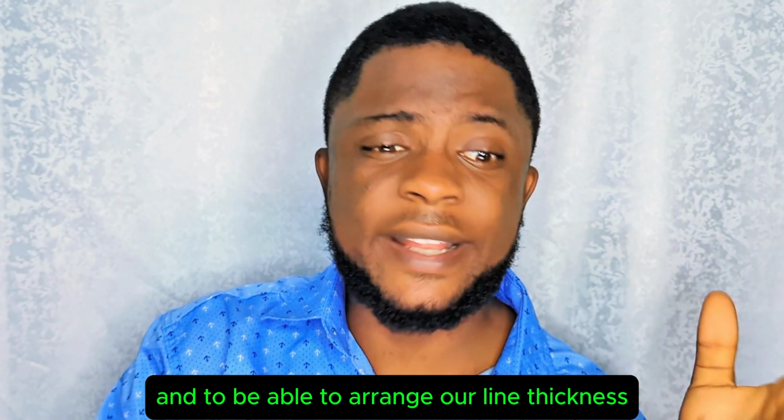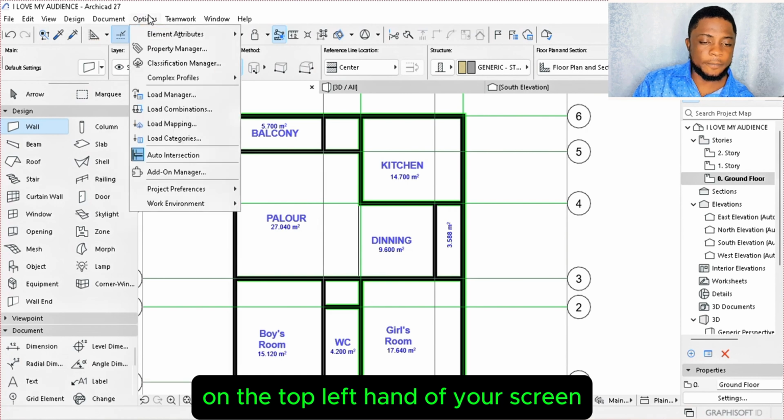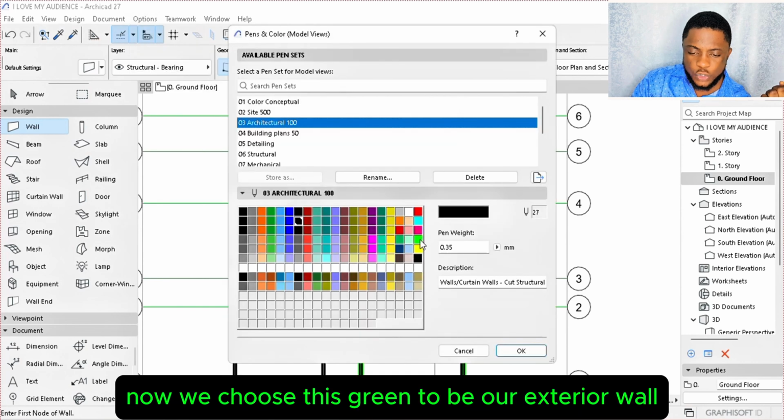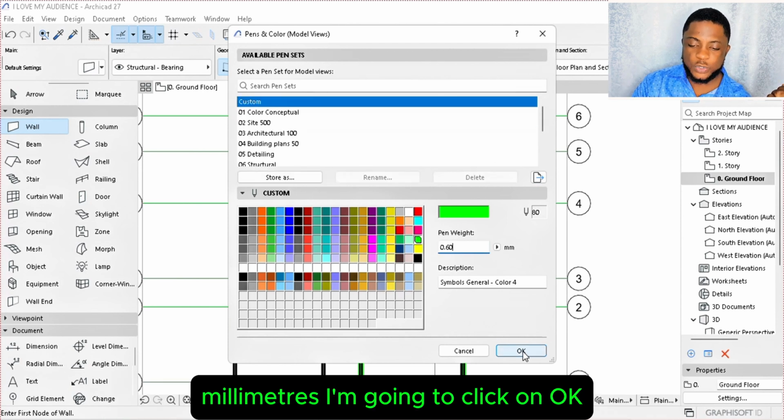And to be able to arrange our line thickness, you navigate to options on the top left hand of your screen. Click on element attributes and move down to pen and colors. Now we choose this green to be our exterior wall, so we are going to make the line thickness to be 0.6 millimeters. I'm going to click on OK.